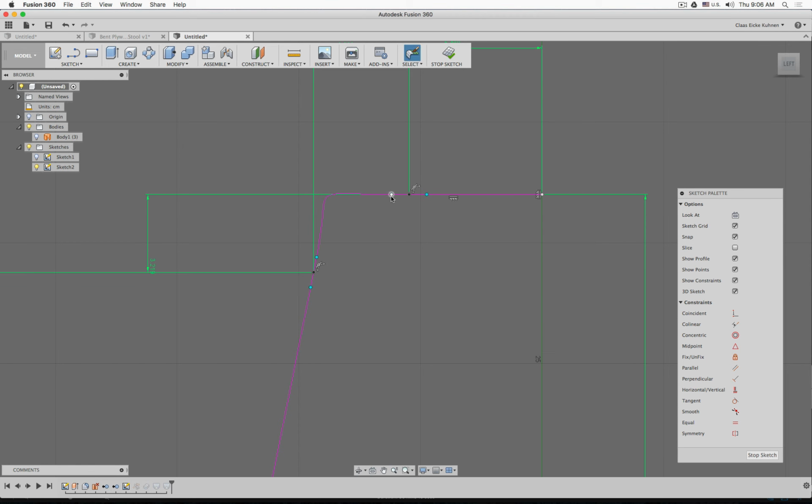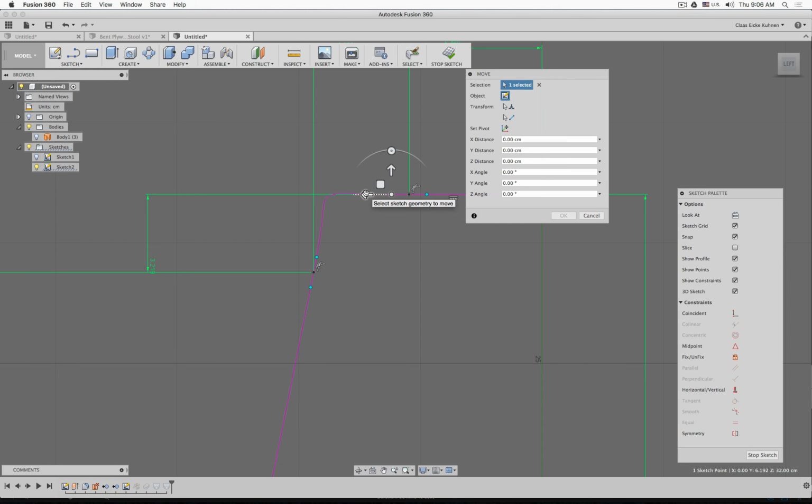And then click this point for the handle, and then very gently adjust them. Just very small adjustments will have actually quite an impact on how the curve changes. And there. And you see also here, I moved this point up and down, but actually because the handle is constrained to be smooth to the line, the handle adjusts based on the direction of the line.